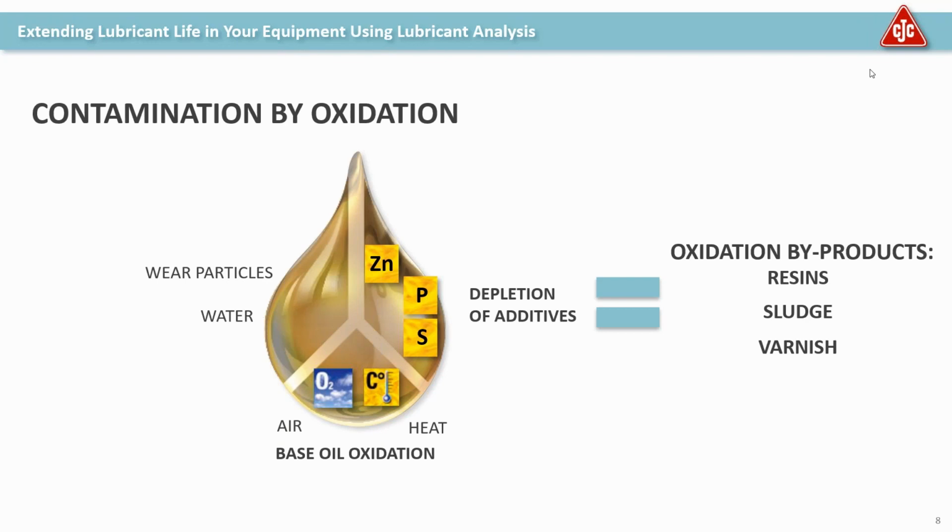That's actually what we pay for. We want them to deplete. We want them to do their job and to sacrifice themselves for the health of our equipment. And so there's, of course, other mechanisms at play here that we need to recognize. One is decomposition from water and heat. That can cause the chemistry to change. The mass of the additives is still floating around, and it's possible that that can be detrimental. But there's also the situation where you have mass transfer of those additives.